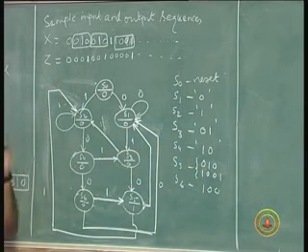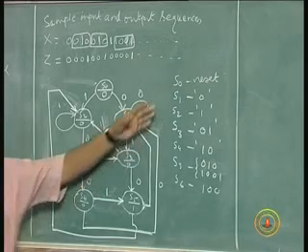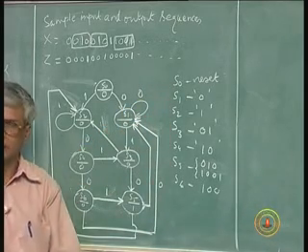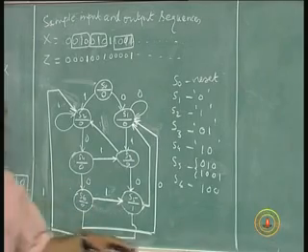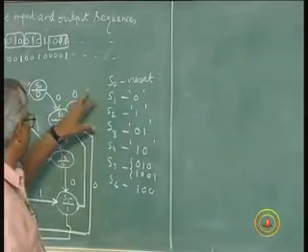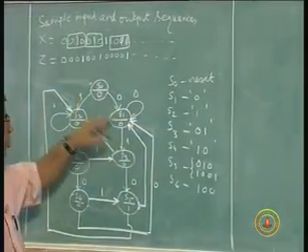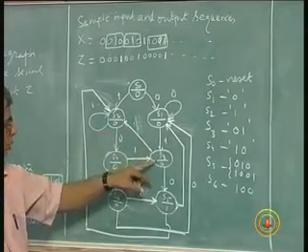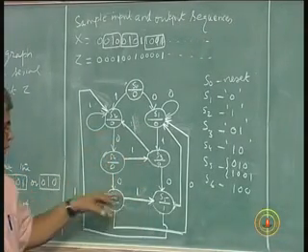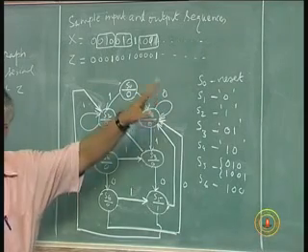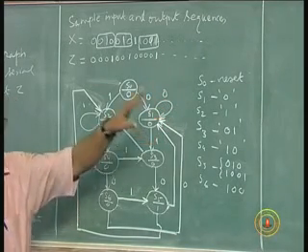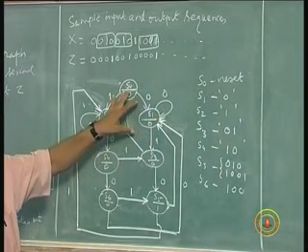Now the diagram is completed. It's 6 states plus 1, 7 states totally. Again, you use 3 flip-flops. You can draw the state graph with the present state values arbitrarily assigned as 000, 001, 010, 011, 100, 101, 110, and then the input x is equal to 0. What is the next state? What is the output? Of course, output is dependent on the state now.